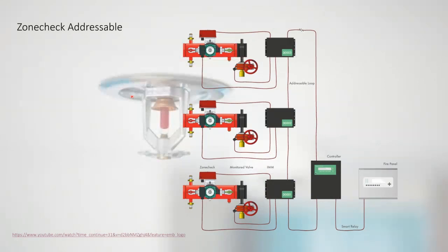And if you don't get any healthy, they can then call out the sprinkler contractor to do that. And save you a bit of money in maintenance, quite a bit of money in maintenance, because the last thing you want to do is have a sprinkler engineer on your site for a week testing all your zone valves. And this can be done in 20 minutes. So it's definitely worth thinking about if you do have a large site with lots of zone valves on it.